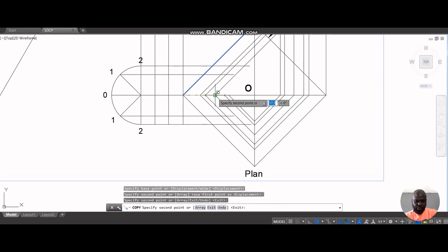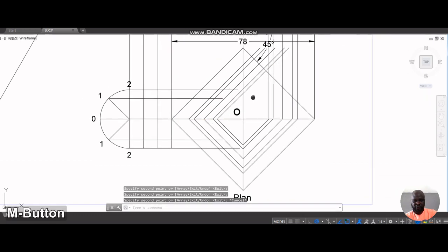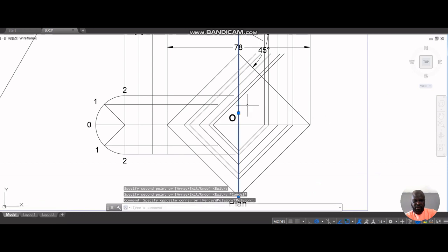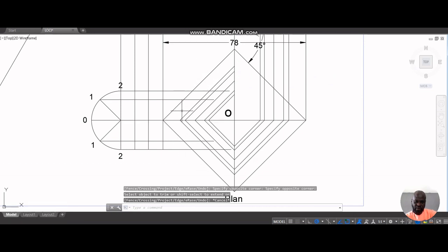Lock it in with your T-square and continue to draw straight lines. All right. So they would intersect this other center line, so to speak. Yeah, so now we're done because we have cut through all of these points.